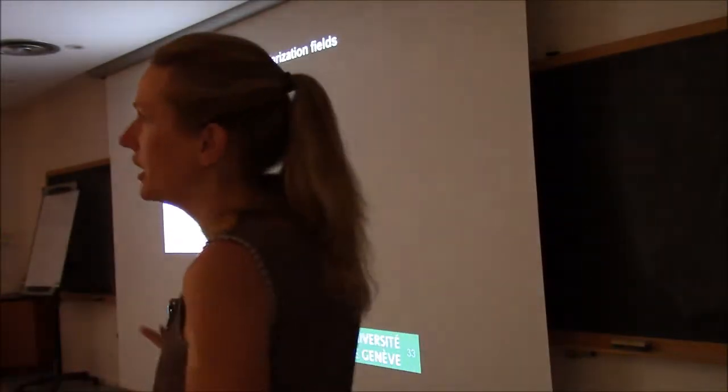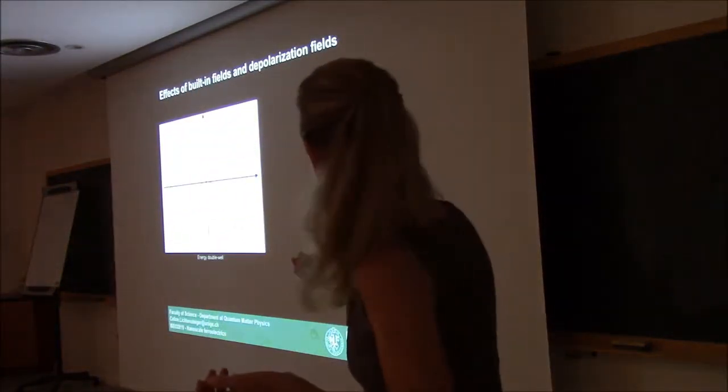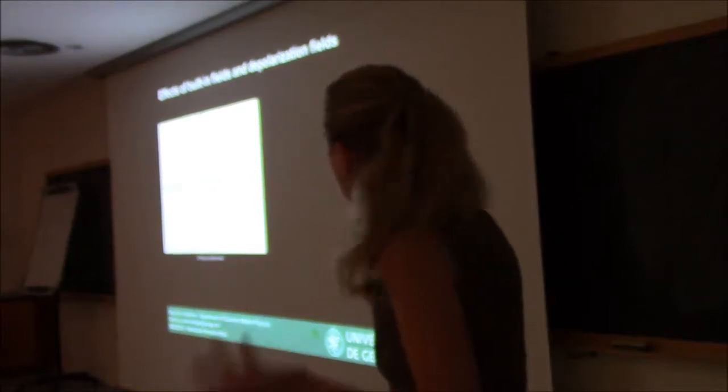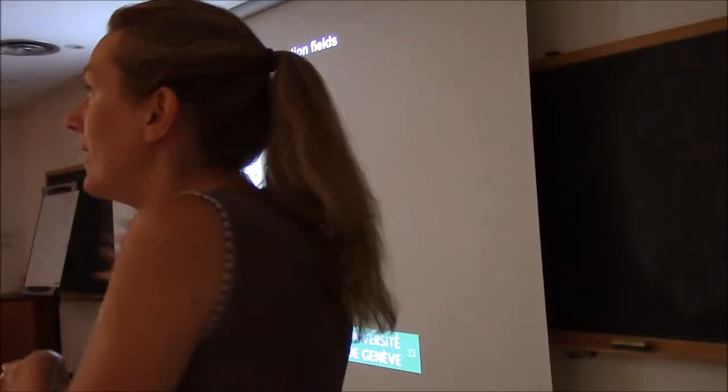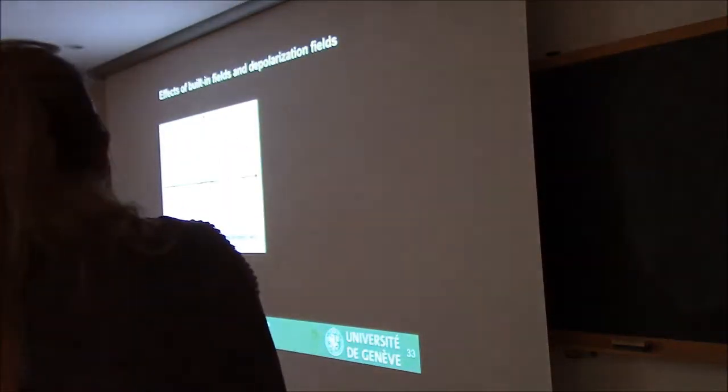Okay, so just to finish with that, in terms of the energy double well that you have in ferroelectric materials, this would represent the value that you have in the bulk. If you add a depolarization field, what will happen is that you make this energy double well more shallower. So you are not only reducing the value of the stable polarization, but it will also be easier to switch or to remove this polarization.